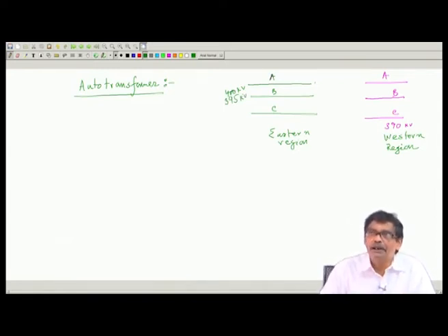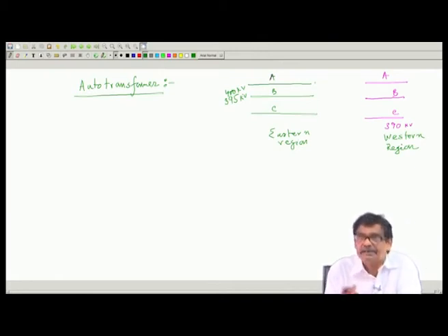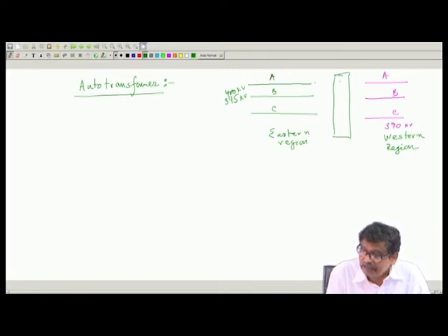But I want to connect them in parallel, so that the flexibility increases: this side can feed power, that side can feed power, and so on. In such situations these two systems can be connected if you connect a 3-phase auto transformer in between. I will tell what this auto transformer is. Through an auto transformer you will be able to parallel them.